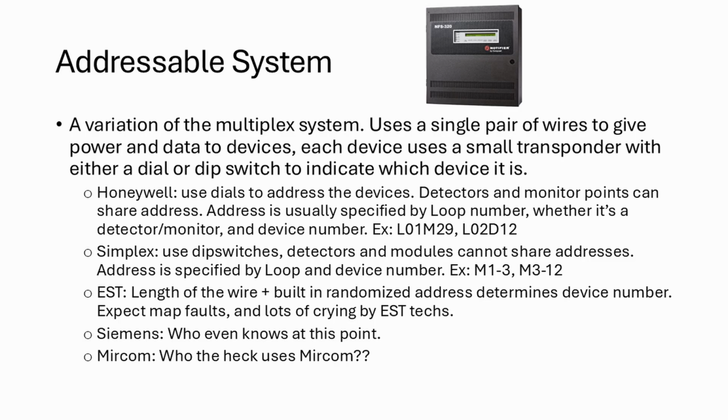Honeywell uses dials to address these devices. The detectors and monitor points can share addresses. Simplex uses dip switches. Detectors and modules cannot share addresses.